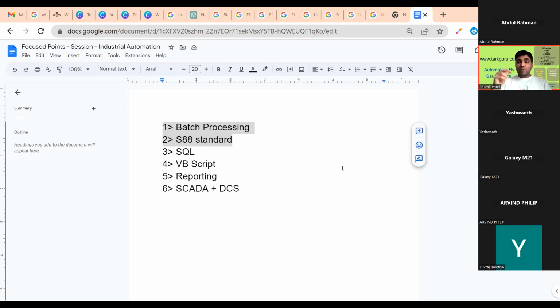So to prepare one batch of chocolate, you need to do the programming of adding logic, mixing logic, cooling logic, and heating logic. That small logic is nothing but the phase. That phase, if you start the adding or cooling, right, that phase will call the equipment module. I told you the equipment module is nothing but the group of devices.